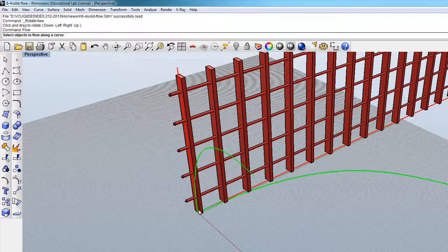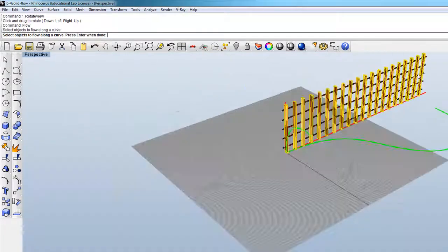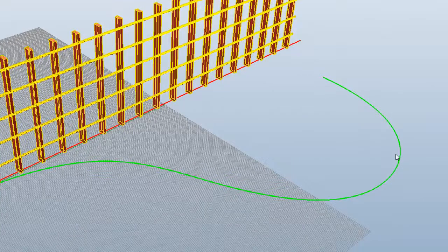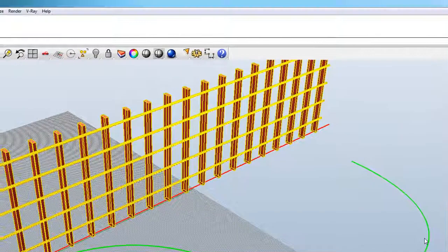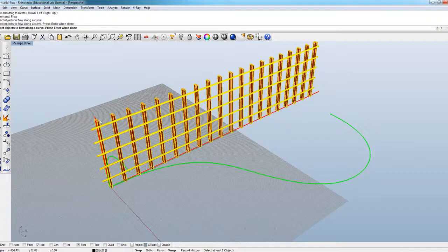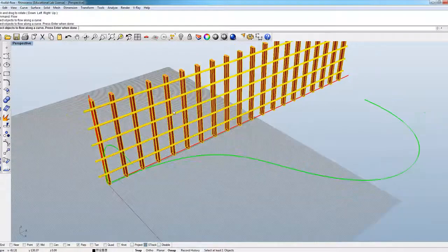And also flow does not need a base surface or target surface. It follows a line. So with this shape right here and with this solid right here and a few lines, we could create quite an elaborate structure. This is a very useful tool while you do your design because most of the time we can easily construct solid shapes like this by simply doing extrusion and repetition. And then if we use the flow, we could really twist and change the form and make it much more interesting.